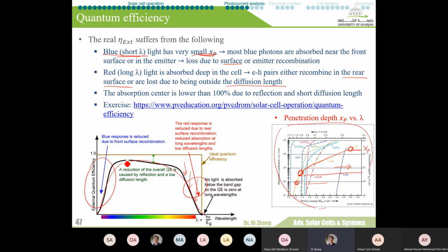You have a plateau in the middle, but in the beginning and in the end you actually have a declining quantum efficiency. Even in the middle plateau, you may expect some deviation or reduction from 100%. For one thing, it is difficult to reduce the reflection to 0%. This is not always possible. And second, we typically expect some recombination losses and some other electrical losses. All of this will reduce the overall quantum efficiency.